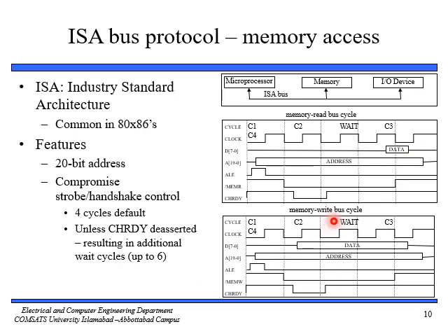Here in the memory write bus cycle, you can see we are putting the address on the address line, we are enabling the latch, and after latching we have memory write, so we are telling which memory to write. Once this memory write signal is low, we are writing during cycle 2 and cycle 3, and that's it.